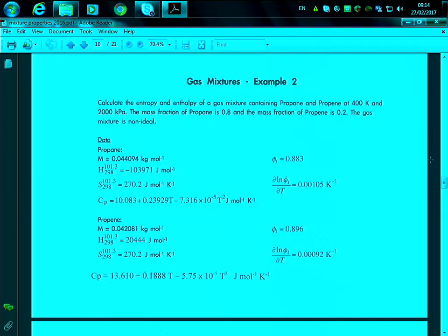So basically what we're going to do is if we have a mixture which is liquid and gas, we will look at the compounds that are in the liquid, and we will look at the compounds that are in the gas. And we can treat each fraction as ideal separately. Okay? So we'll treat all the liquid because it's likely, let's say, if we have a certain temperature, that at that temperature volatiles have gone to the gas phase.